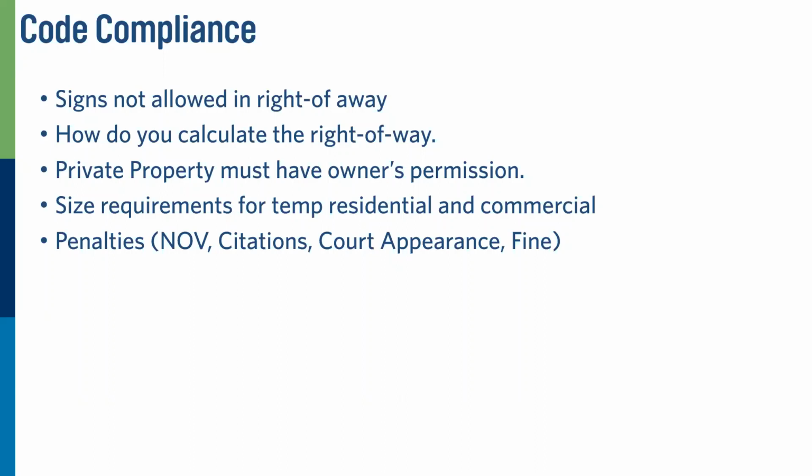So make sure you're at least 18 inches behind the curb line, and you'll be good with code. Well, it's not predictive. A says keep it 18 inches from the curb line, and B says not in the front line. Right. And we're going through some code revisions right now where we're going to get some of that stuff clarified.